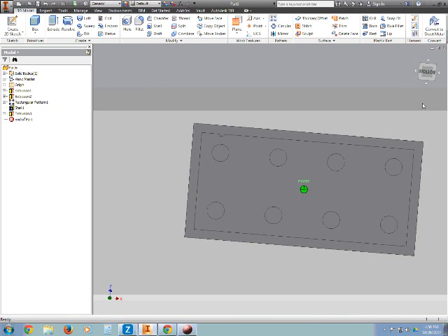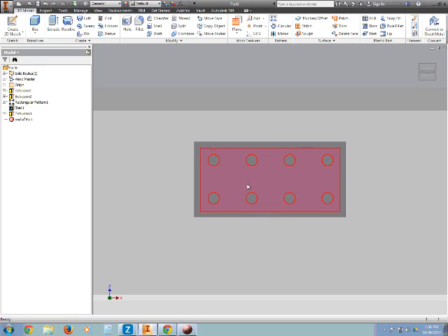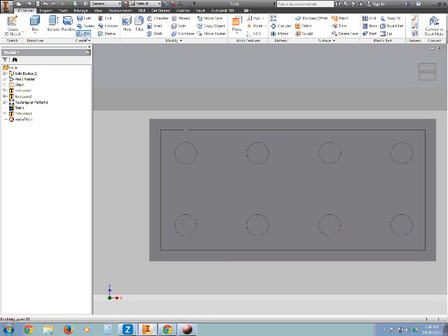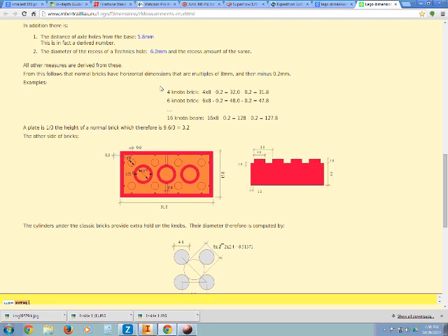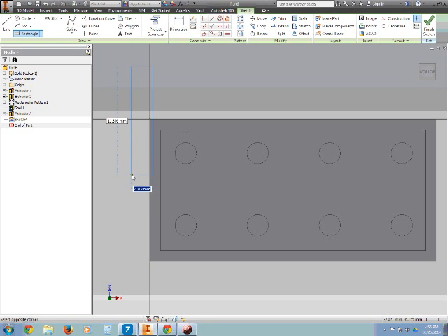We're now ready to draw the one on this side. Again, square this up a little bit. Zoom in. I'm going to go ahead and, again, on this surface, right-click, choose New Sketch, and draw another rectangle. I'm going to go ahead and dimension it as I go. Let me go back to the internet and show you. So this one is, again, 0.3 this way, 0.6 tall. So this one is 0.3. It asks for the horizontal distance first. Tab and 0.6. Then press the Enter key.